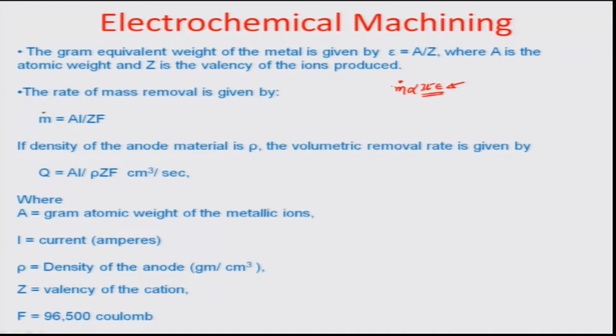Okay, so that's the material removal rate, the rate of mass removal, and we can call this by putting a very interesting term here, which is the Faraday constant, and we assume this movement of material as moles. You know that 1 mole is 6.023 times 10 to the power of 23 atoms or species or ions or whatever it gets dissolved.